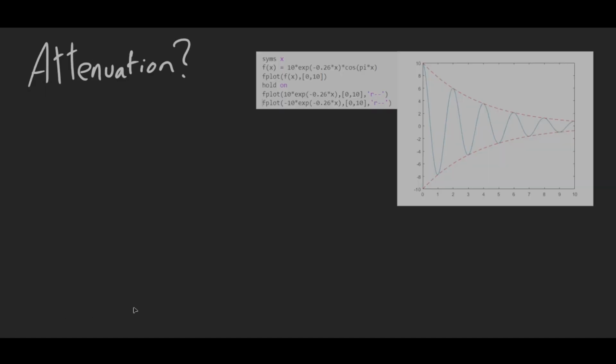Okay, there's one other thing you need to consider with your traveling wave, and that's if your wave travels through a lossy medium. So when your wave travels through a lossy medium, the wave amplitude will decrease exponentially the further the wave travels into the lossy medium. So we can put this in terms of an equation. It's just the same as before, just one extra thing. y of x and t is equal to A, and here it is. It's just e to the minus alpha z.